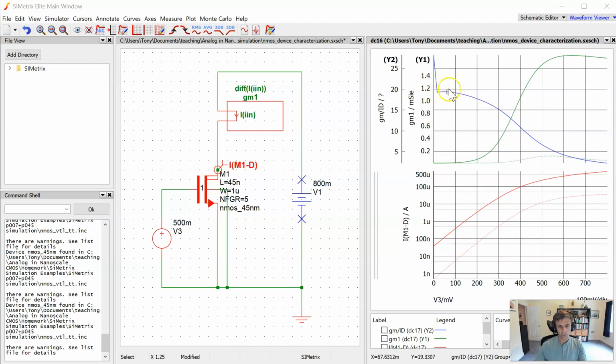So the lower transconductance here than we would expect based on N extracted from this plot may be due to some series source resistance due to a lightly doped source region or something like that that's sort of degrading the small signal transconductance of the MOSFET. So that would show up in this plot here, might not be as evident in this plot here. So I would tend to believe the value of N extracted from this plot a little more.